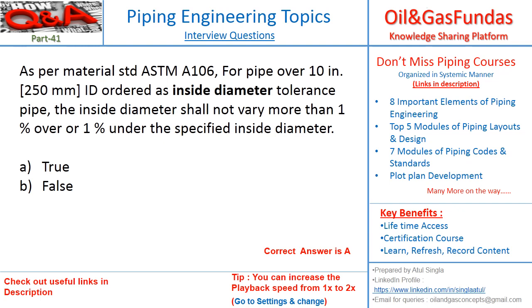This is one of the important clauses mentioned in ASTM A106. We are talking about inside diameter tolerances. Whenever we order a pipe which has a size of more than 10 inch, the manufacturer may have some discrepancy in size. The size may vary from the desired one. So what kind of variation is accepted?